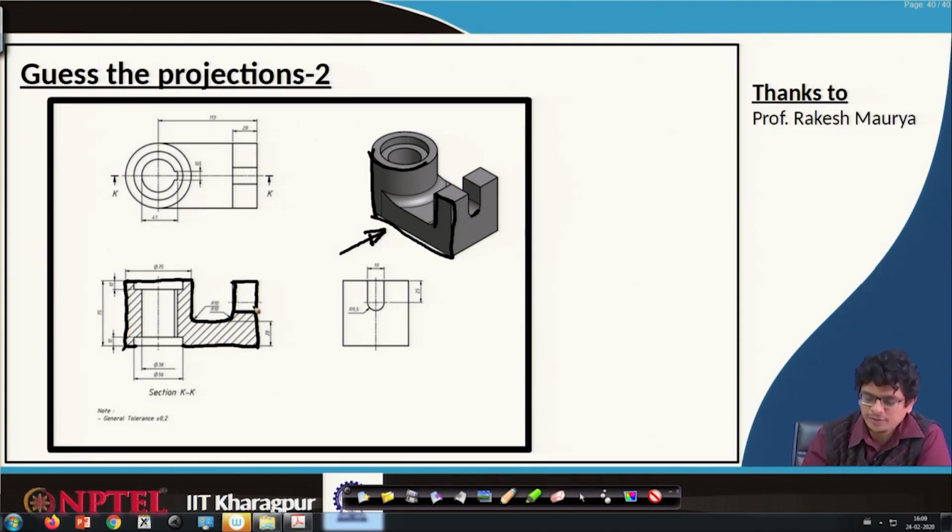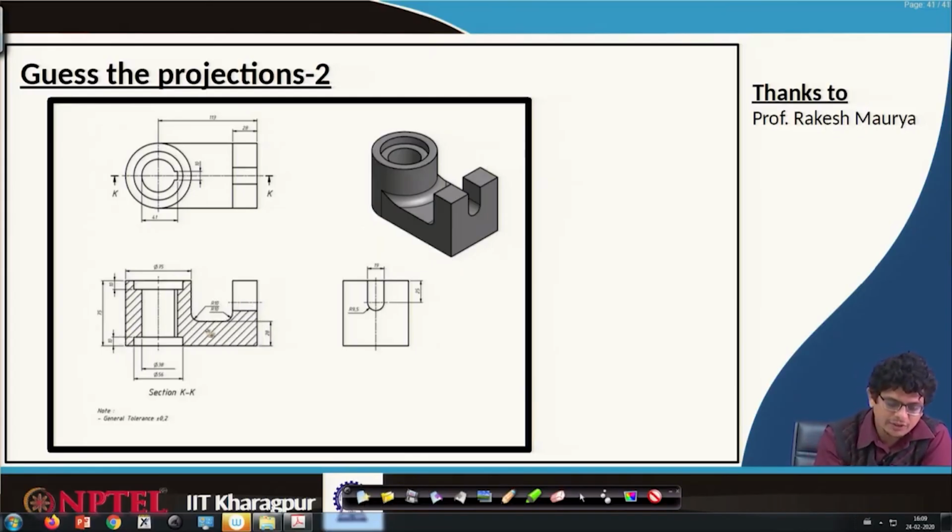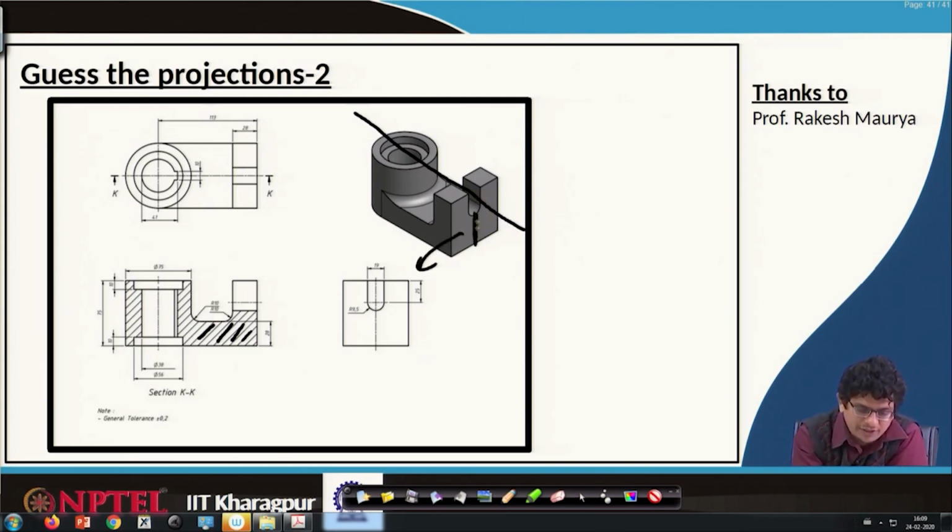Remember, for any drawing, whenever such kind of inclined lines are there, that means it is a cut sectional view. Usually we cut at center, middle, remove the first part, the remaining leftover portion we will show it like a cut section. This cut section can be at middle, it can be at the edges also, usually we go ahead with.